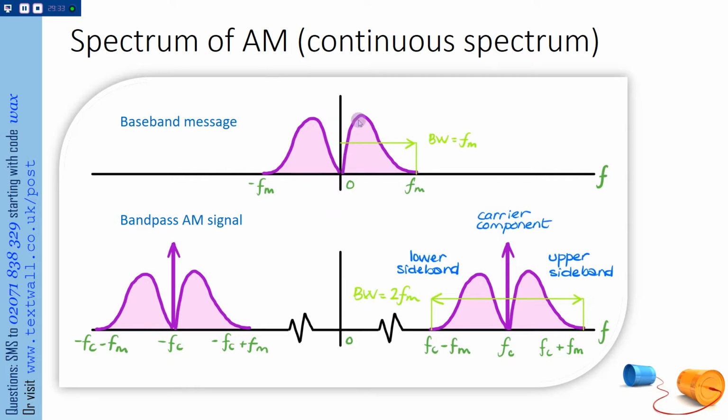So, a signal that looks like that, the shape of the spectrum hasn't changed at all. The only thing I've done is I've added this negative part. And if you notice, it's a reflection. So some people in the exam took the positive sideband and repeated it here, but they didn't reflect it. So I've tried to make it look clear enough so that one is a reflection of the other. So the upper sideband is a reflection of the lower sideband. Okay? So the total bandwidth doubles.